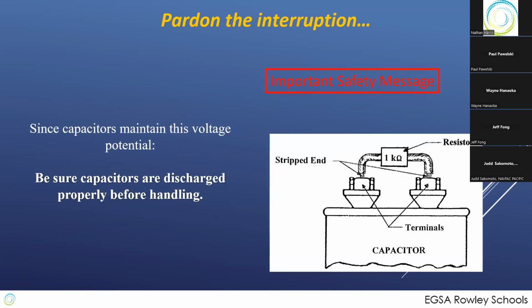So here's the important thing. Your technicians will most likely have with them not only a multimeter to measure the amount of voltage potential across capacitors and everything else, they'll probably carry something like this: a very large capacity 1 kilo ohm resistor with the leads on it being insulated down to just the ends. They touch this to the prongs on the capacitor to allow it to discharge.